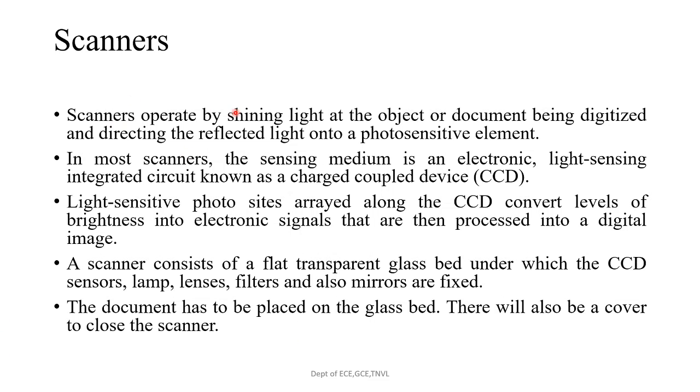Scanners. Scanners operate by shining light at the object or document being digitized and directing the reflected light onto a photosensitive element. In most scanners, the sensing medium is an electronic light sensing integrated circuit known as a charge coupled device. Light sensitive photosites arrayed along the CCD convert levels of brightness into electronic signals that are then processed